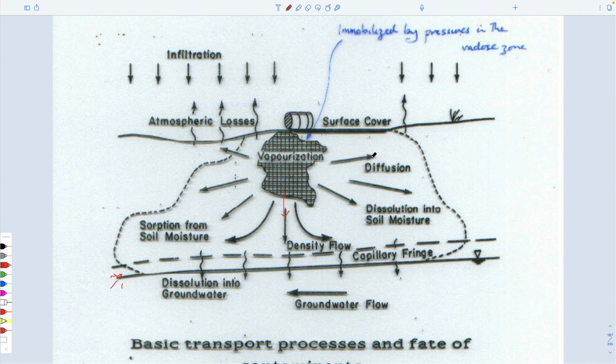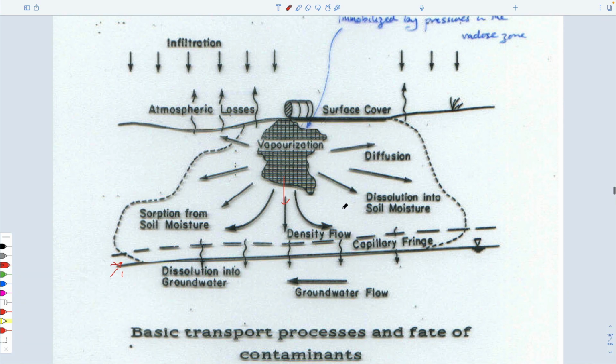It will diffuse in the air. It will diffuse, since this vadose zone is partly air and partly water, as well as quartz. It will diffuse within the air and the fluid, much faster in the air. Smelling a scent in the room is much faster than that traveling in water. And it will also be carried down by infiltration of groundwater, by so-called advection.